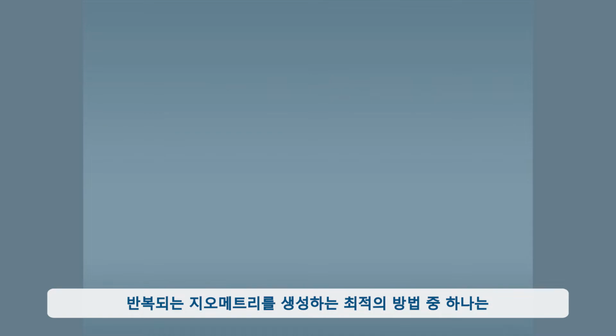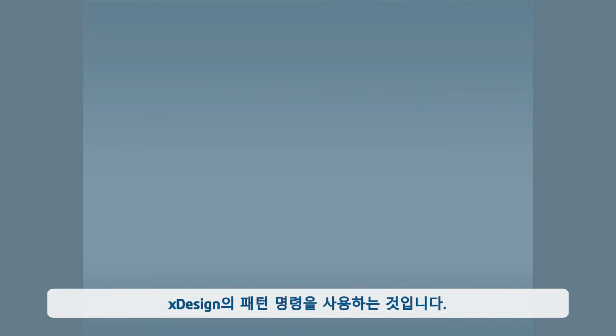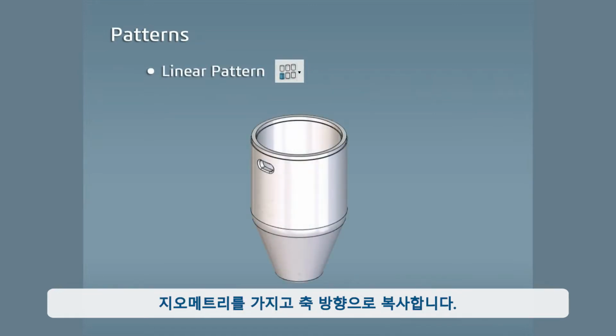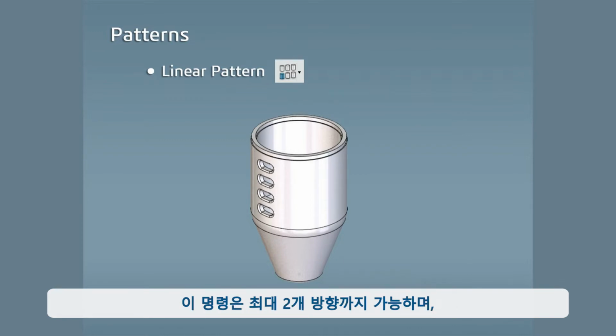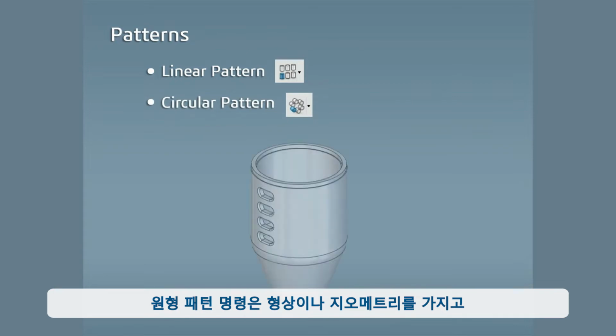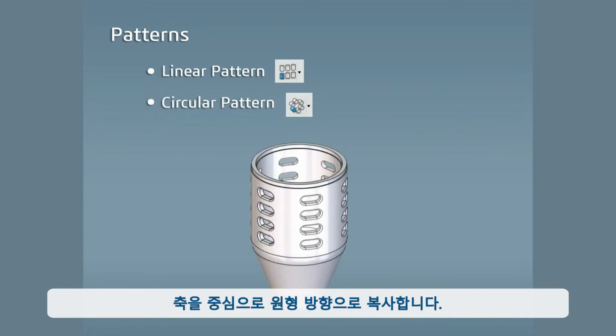One of the optimal ways of creating repeated geometry is using the patterning commands in Xdesign. The linear pattern command takes the features or geometry you select and replicates it in an axial direction. This can be done for up to 2 directions, where the angle between the 2 directions is determined by the selections that are made. The circular pattern command takes the features or geometry and replicates it around an axis in a circular direction. This can be done in 2 directions from the original instance, and the angle it spans can be set to a specific value.